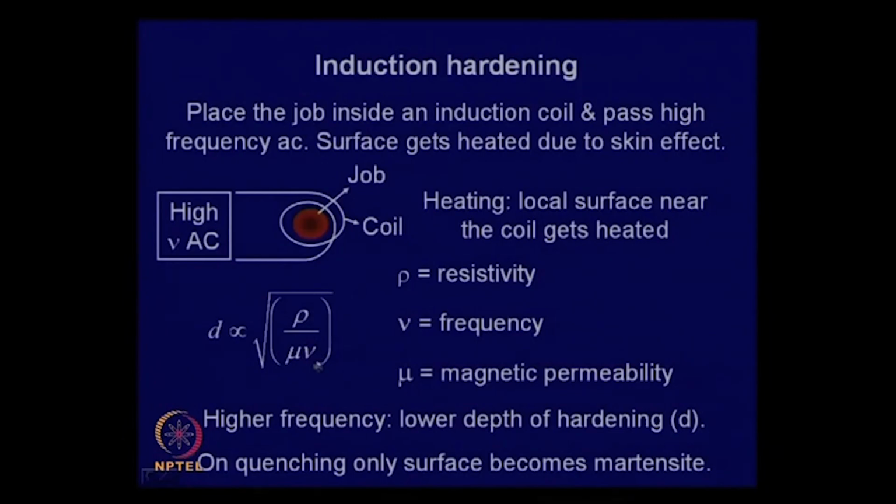And if you use a very high frequency, because of the skin effect, the depth of hardening is low. So, depth of hardening can also be increased by increasing the hold time, because if this gets heated, then this heat will get conducted and move towards the core also. So, if you have a longer heating time, you can control the depth of hardening. So, by controlling the frequency and the hold time, you can control the depth of hardening, and this primarily